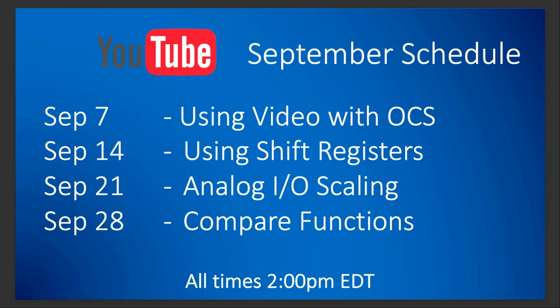And then we're also going to take a look at compare functions. Compare functions seem simple, but we have some little used compare functions, such as time and date compare, which you really should know about, because if you've got any kind of a scheduling application or a scheduling aspect to your machine, those compare functions come in really useful.